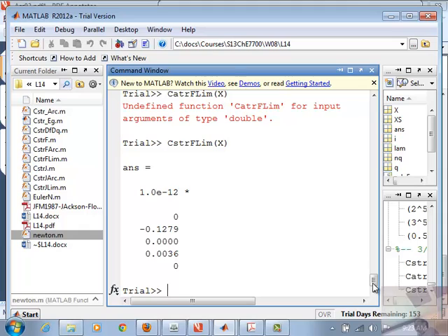What is the condition that we wanted to impose? That the Jacobian must be singular. Determinant must be 0, right? So I could make a call to the Jacobian CSTRJ, passing the first 2 values, x. What do I expect this function to return? I expect it to return a 2 by 2 matrix, which will be the Jacobian, using the current values of x1 and x2, that is a and t, at the solution.